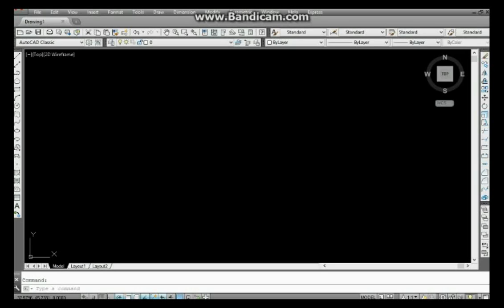Now first of all, you have to create your limits. After creating the limits, you set your units for drawing. Normally, if it's an engineering drawing, due to your company specification, you're drawing either in inches or in millimeters, which is imperial or metric. Now you set your units, and you set some certain things like your dimension, your text style, and